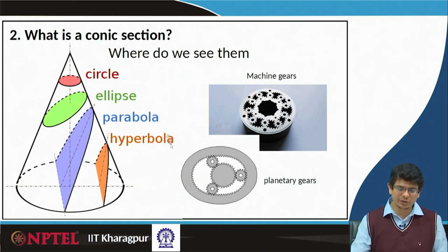So, here let us look at that planetary gear. If the driving motion is done by this circular gear, if it is centered, we will be in a position to transfer this power to this gear and that gear, and finally through this planetary gear arrangement also. This planetary gear sometimes comes here, sometimes goes up through the major and minor axes, and transmits the power to the required locations. This is the way we get power transmission from these circular and elliptical kinds of gears.